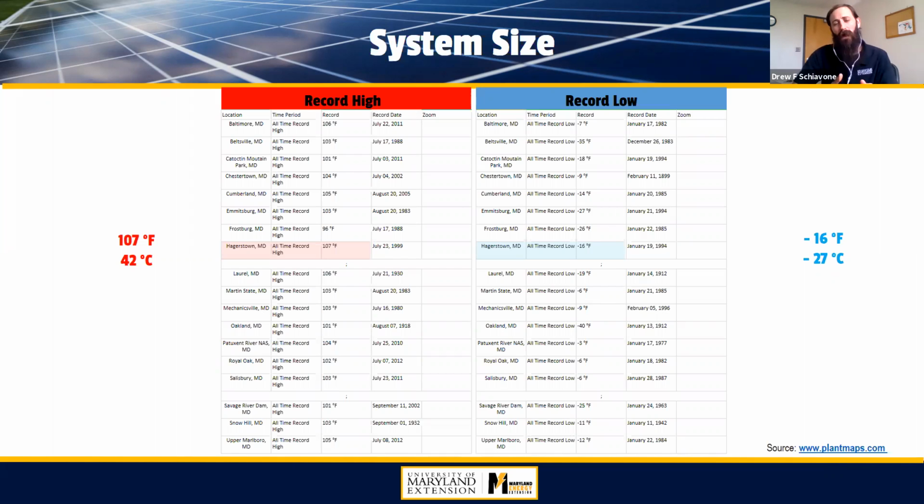So I just want to point out the importance, when you pick out the inverter to match this PV system, the solar modules, that you want to make sure that you're within the proper voltage range. And to do so, I typically look at the temperature range. So I'm going to share a brief example. I won't spend a whole lot of time on this, but I use the most conservative temperatures that I could find for this example.